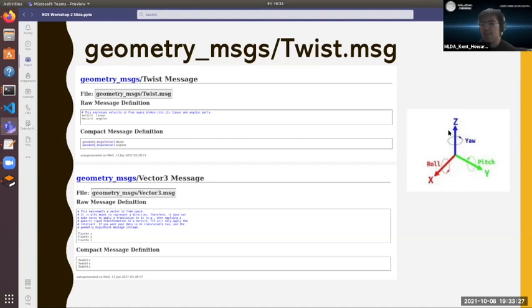If you point the thumb of your right hand in the direction of the vector, then you get the rotation direction of the vector. So Z corresponds to the yaw, which is the only angular velocity that we can use.